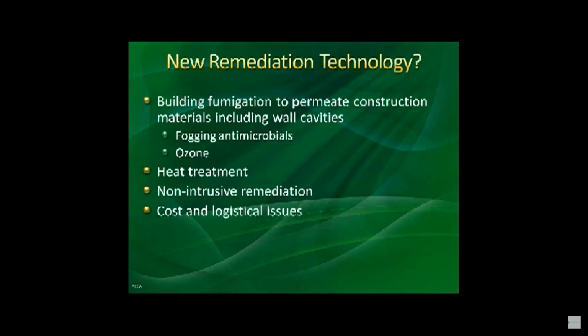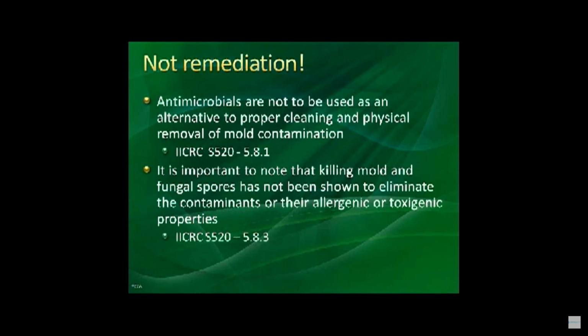There's new remediation technology out there. We call it fogging antimicrobials. We call it ozone. We call it heat treatments. Non-intrusive remediation, because of the cost and how you can apply it so effectively. That's remediation? No, it's not. Antimicrobials are not an alternate to remediation. They're used in conjunction. Remediation means the physical removal of that mold contamination.